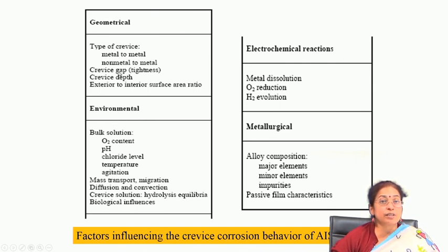Again, crevice gap is very important, because the lower the gap, the smaller the amount of electrolyte, and the larger the gap, naturally the higher the amount of electrolyte in the crevice site. So accordingly you will find that the attack rate will also vary.